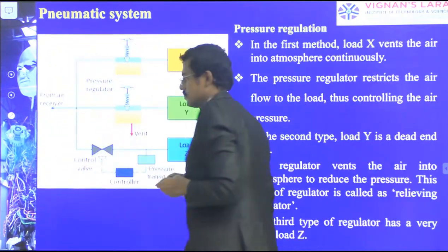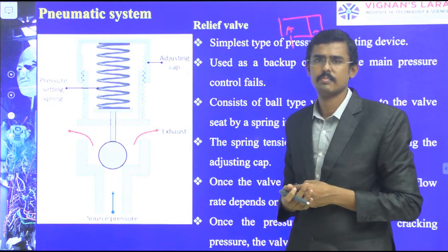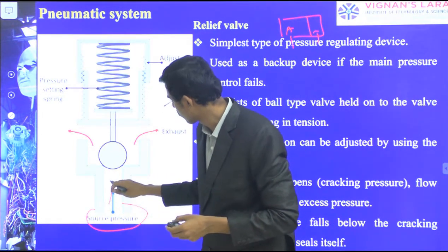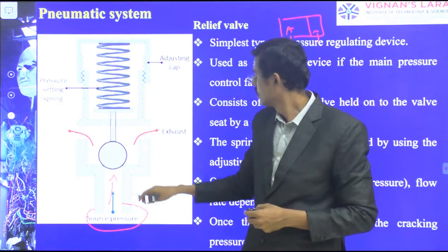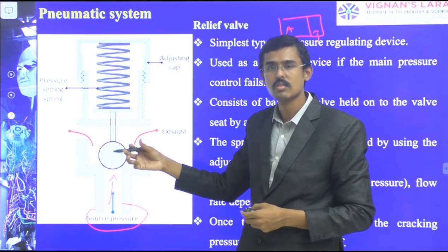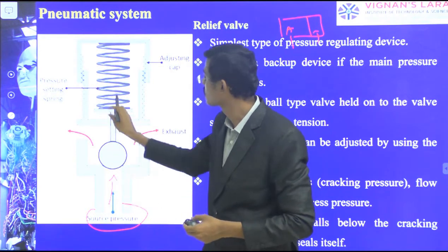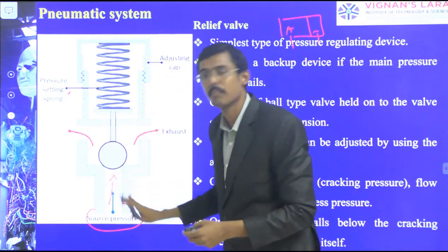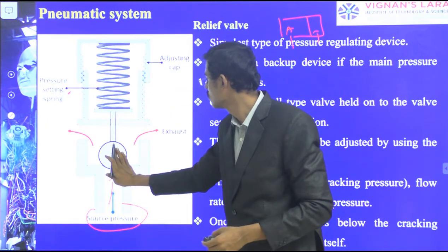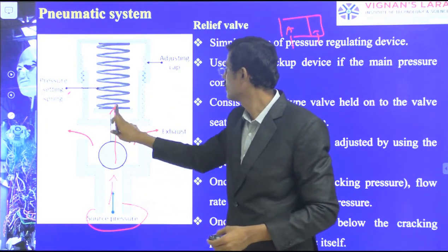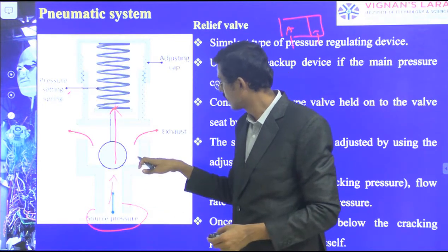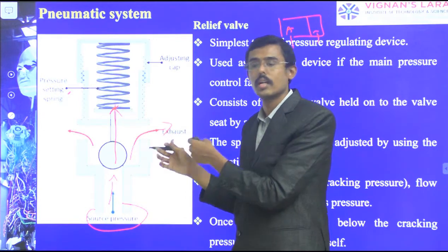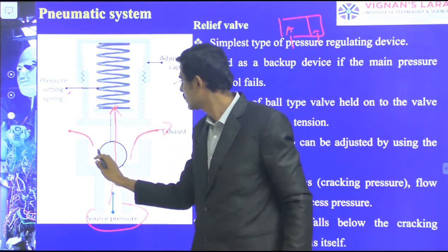In this setup, the air source of pressure, the pressurized air comes in. Here we have a control valve. So this can push the spring return. The spring return setting I have kept so that when the pressure is applied, this spring has to move in the upward direction. Therefore, the pressurized air can take exit through the available outlets. This is one available outlet, and this is one available outlet.